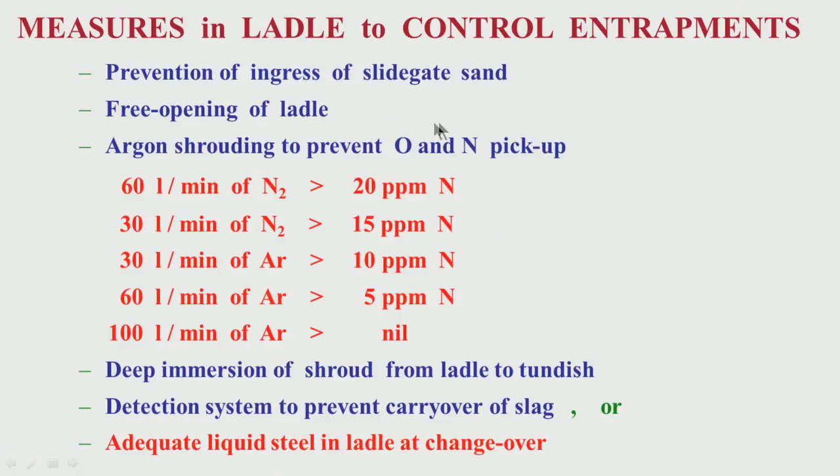Sometimes it is required when the ladle is not opening free, you have to use an oxygen lance to open it. In that process, the liquid steel gets oxidized. So, that is not desirable. It should open free, and for that only we are using slide gate.